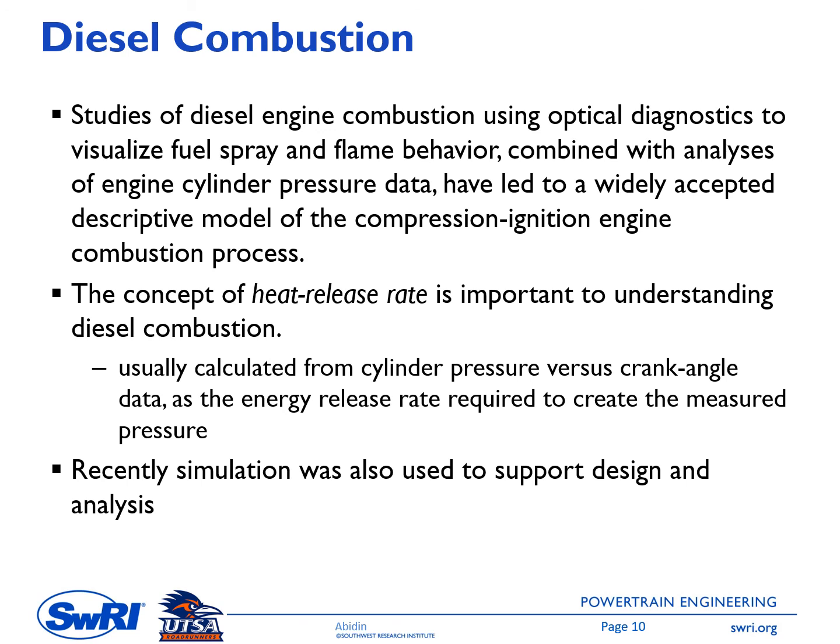And then similar to the one in spark ignition engine, we can also use the concept of the heat release rate here to understand the diesel combustion process. This heat release rate is obtained from the measured cylinder pressure. So it's the same as the one in the spark ignition engine process. And also recently, simulation was used massively to support the design and analysis of a diesel combustion system.